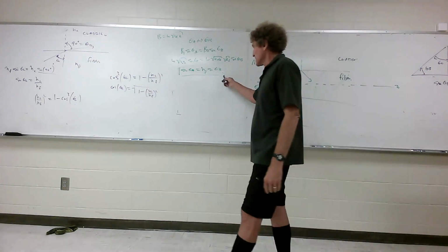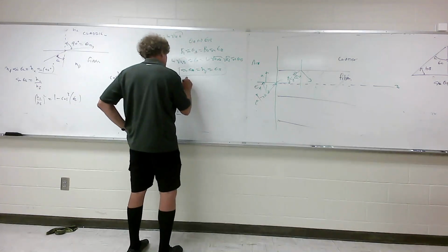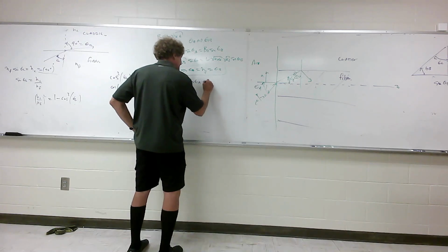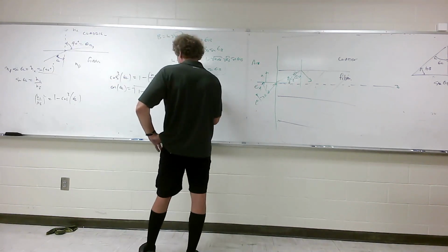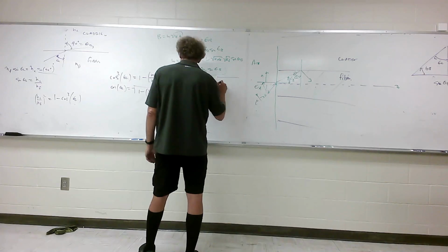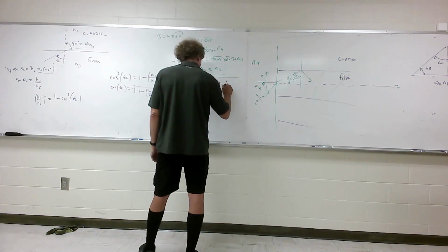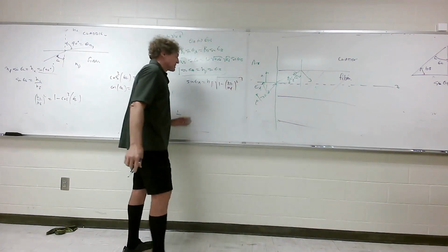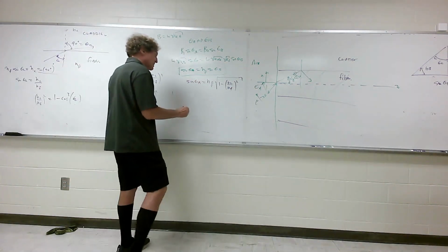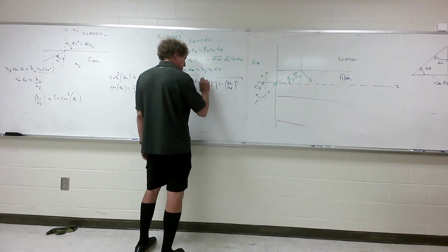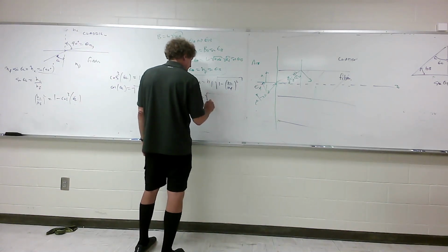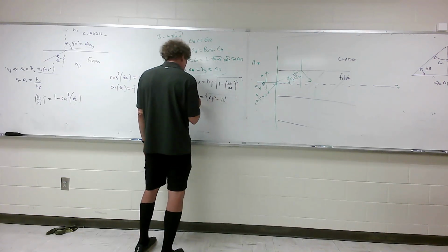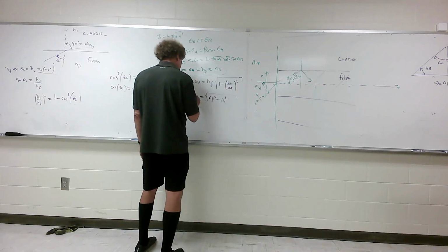And that's where I make the substitution in here. Now I can say, you need to write this part down. The sine of theta a is equal to NF times the sine of theta b, which is going to be square root of 1 minus (NC over NF) squared. And I think you can take the NF through, and that's the way he does it in the book. You can take the index of refraction of the fiber inside, he has a square root, and this will be of NF squared minus NC squared. And that's the sine of theta a.